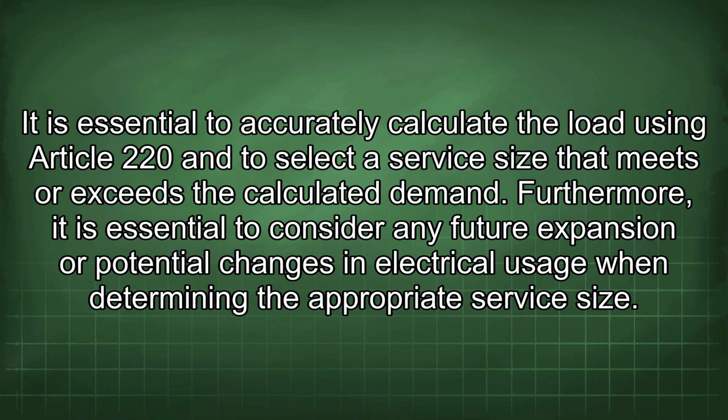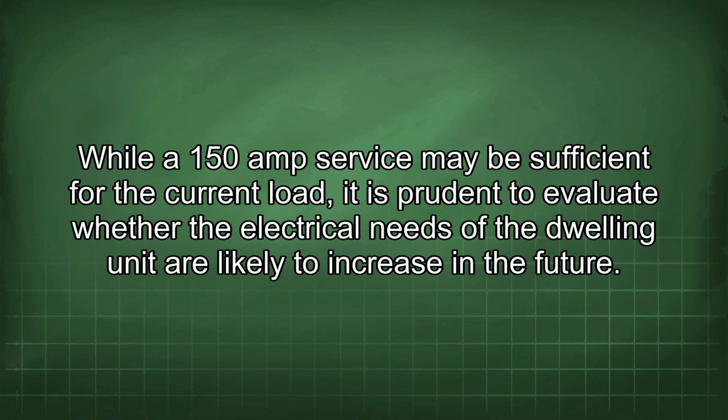It is essential to accurately calculate the load using Article 220 and to select a service size that meets or exceeds the calculated demand. Furthermore, it is essential to consider any future expansion or potential changes in electrical usage when determining the appropriate service size. While a 150 amp service may be sufficient for the current load, it is prudent to evaluate whether the electrical needs of the dwelling unit are likely to increase in the future.